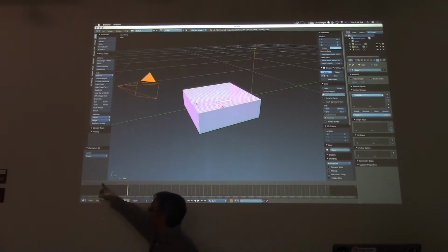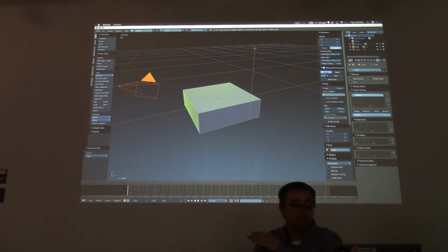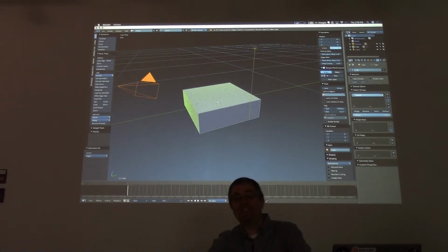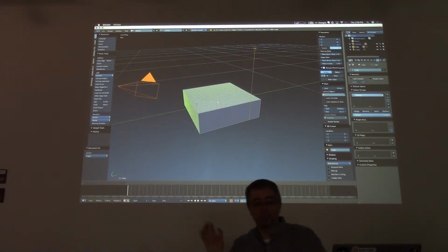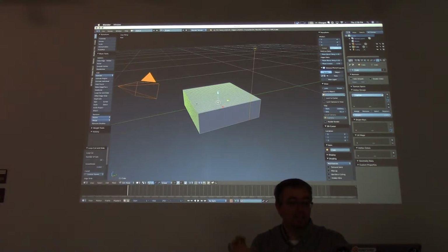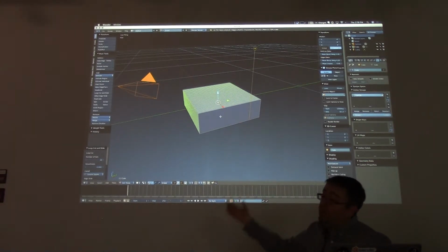So we're going to do 30 cuts, and then I'm going to press my left mouse button once to accept that number of cuts. And at this moment, I can actually move all those cuts around, but I don't want to move them. This is why it's called loop cut and slide, right? I can make these loop cuts, and then I can move them to one end of the box. I actually want them to stay perfectly proportional, so now I'm going to press the left mouse button a second time, and they become fixed. All right? So at this point, all these cuts are now made.